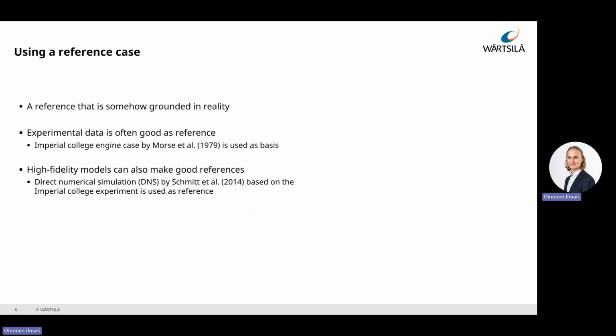It is beneficial to base the simulations on a case that has good reference data available. It makes it easier to validate whether the simulation is behaving correctly. Measurements from experiments are great as reference data, as they are by definition based in reality. In this case, the experimental engine set up by Morse et al. is used as the basis.